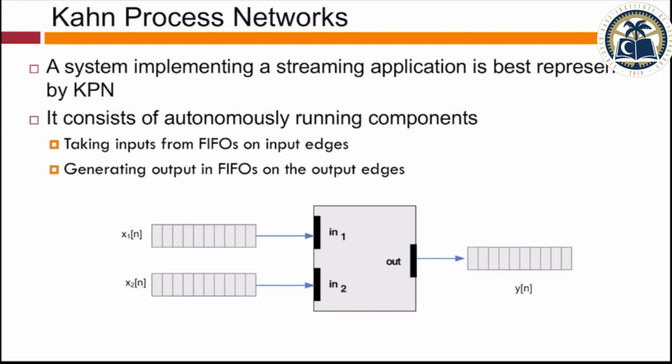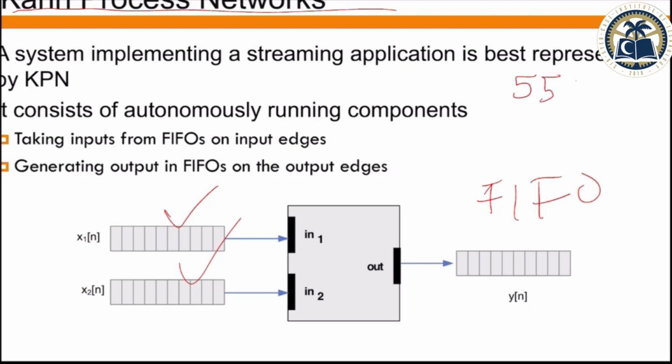So either you say no, I want everything to work all the time. That becomes a very challenging problem to solve at a system level, once you are an architect designing a system level architecture. So the easiest approach is that you make the slowest one figure out how little time it will get to execute in real time, and design every block according to that, because every node has to be designed differently. And then there is something called Kahn Process Network, where all the inputs you generate, you put in FIFOs.